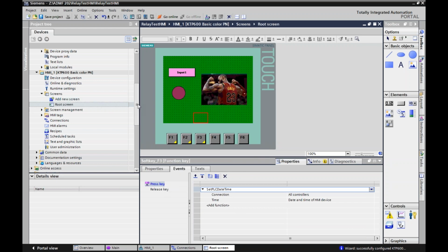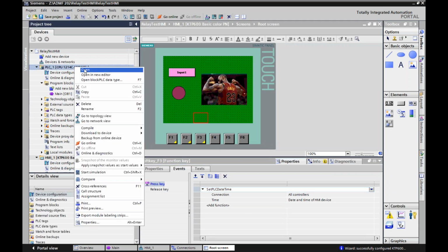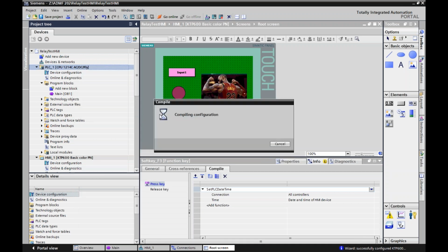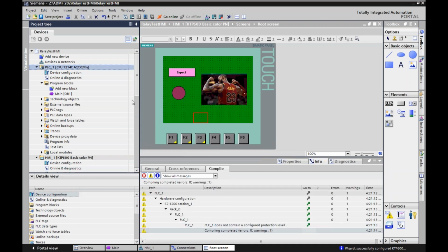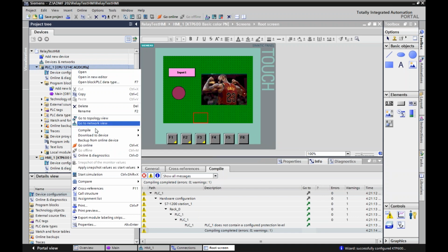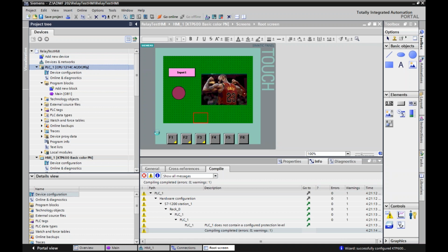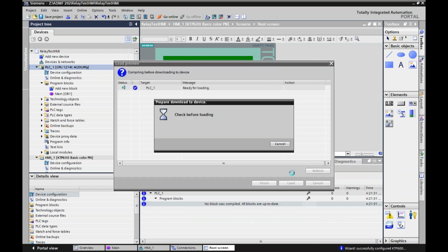So we'll go from there. And so now here comes the next fun thing. First things first, download the process to the PLC and make sure everything is set up right, good to go, because if you don't, you could have issues. So I'm going to download all this to the device, just to the PLC. Make sure everything is operating perfectly.